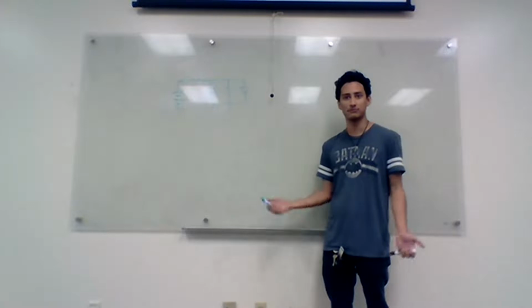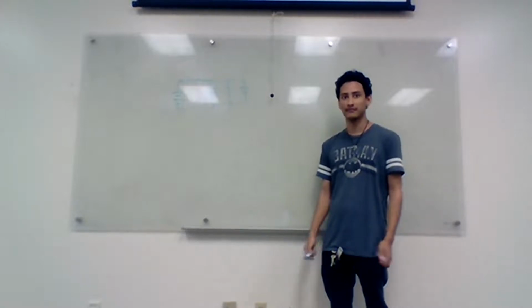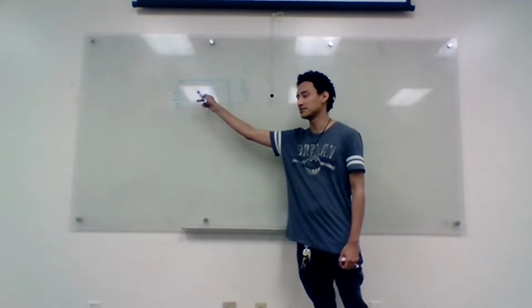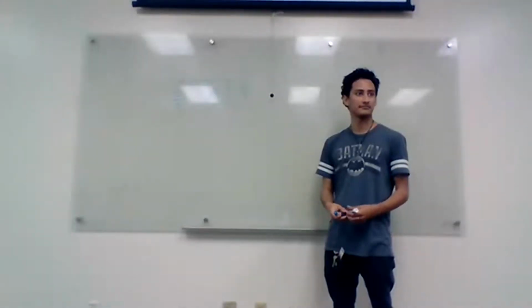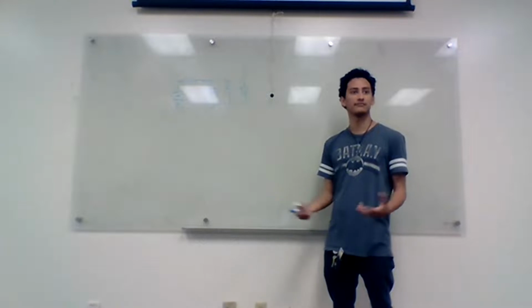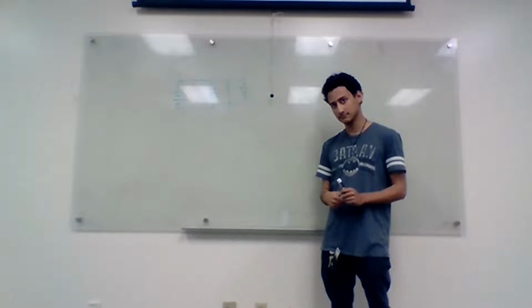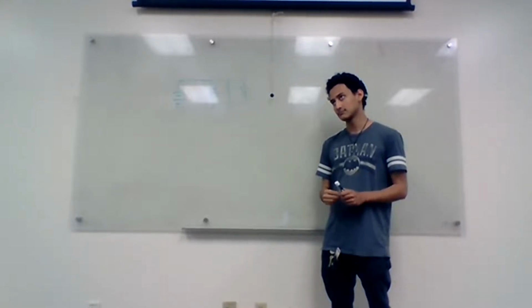KCL equation is going to be a little bit more complicated. If I say that this diode's area is 25 times bigger, what does that change? Can you guys solve that? I think if they're in parallel, can I just combine the diode into one with 26 times the area of the small one?